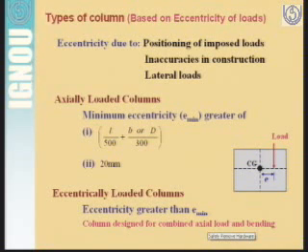The main difference you will find between the course material and the new code is that, based on the earlier code, M15 concrete is also used in many problems, but in the new code M15 concrete is not allowed for the construction of most buildings. So there we start with M20.